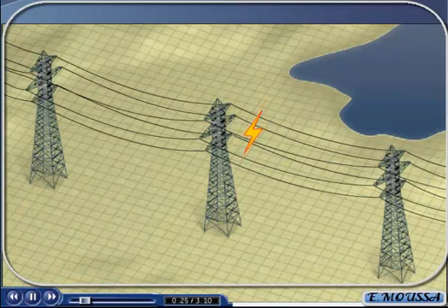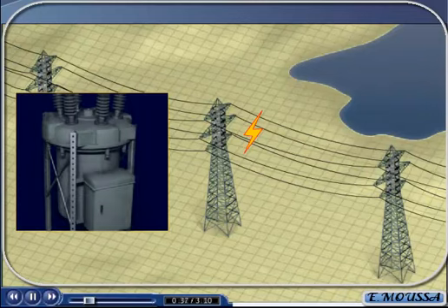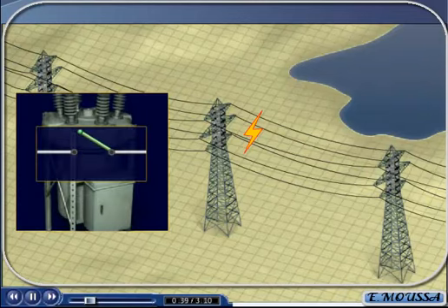If lightning strikes a transmission line, it ionizes the air, which reduces the resistance between the different phases of the line. This reduced resistance allows for a path for current to flow, and hence creates a fault. Once the transmission line is tripped and the fault is cleared, the ionized air is removed and there no longer exists a path for current to flow. Closing the transmission line circuit breaker at this point would re-energize the line and transmission of power could resume.